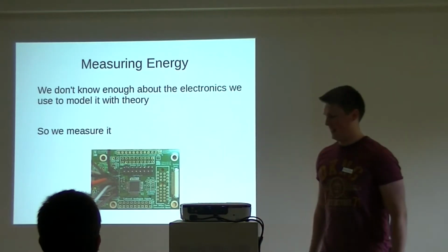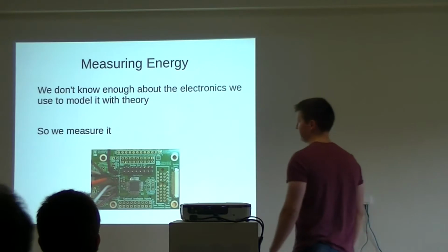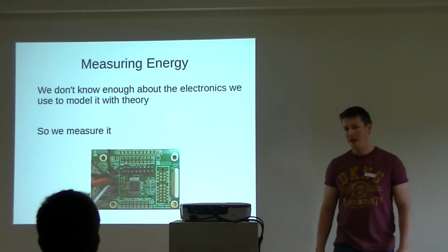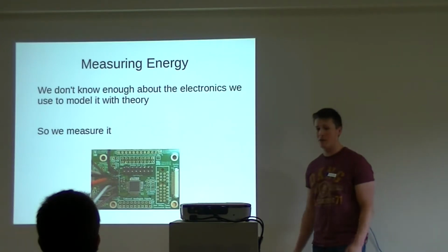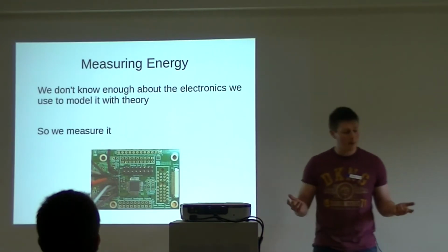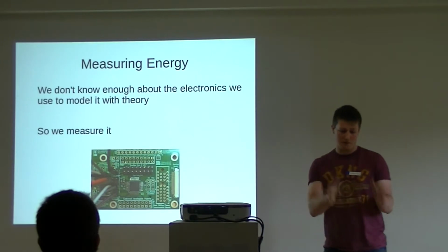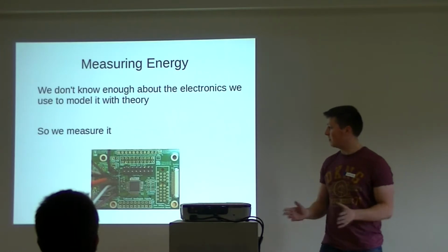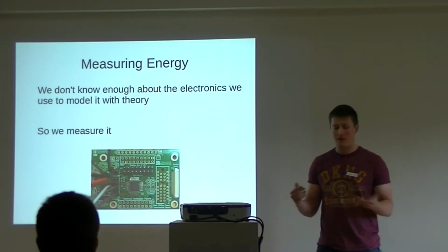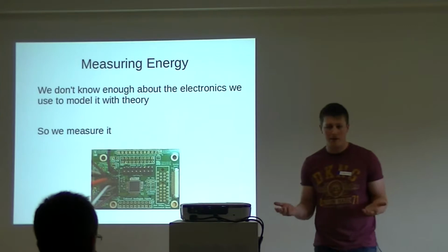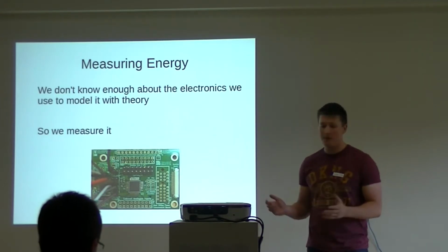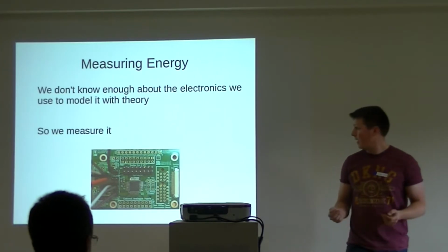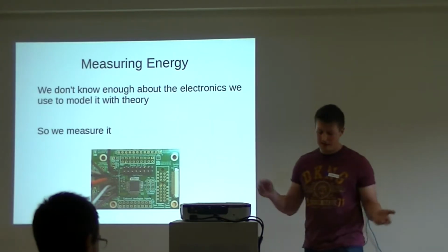But because it's so complex, we don't try and derive it from that theory, we measure it instead. So we will do some empirical measurements and try to assign to each hardware block, say, I2C block, this operation takes this amount. If I want to send 8 bits of data, it's going to take X amount of joules. If I want to receive some, it's going to take Y amount of joules. And then we can minimize our energy by saying, oh, we don't need to do this access, we could cut that out. Our energy is going to go down by this amount.